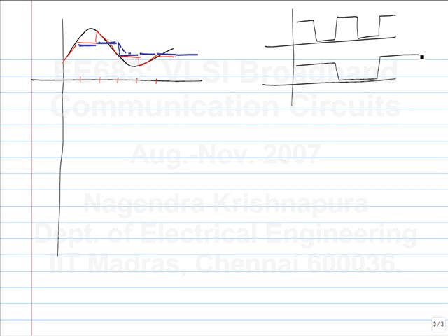How often are you sampling with this? At best by 2, right? So that is the problem. So you can't use it directly like this. What happens is, let's say the switch is on when the clock is high, so you are taking a sample here and the next sample is here. And this sample is held for this entire period T, but your sampling rate is half.